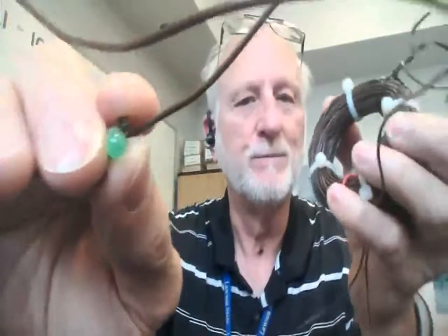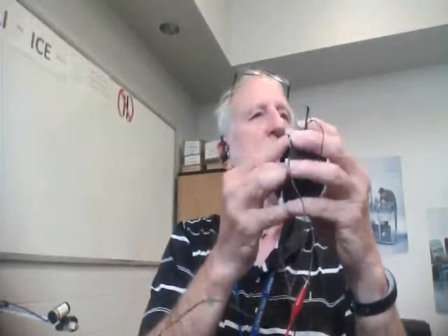So what am I doing? We're reducing in voltage, without a connection. There's no connection between this and this. Now what determines the amount is how close, what we call the coefficient of coupling, how much magnetic field we can couple from my primary over to the secondary.